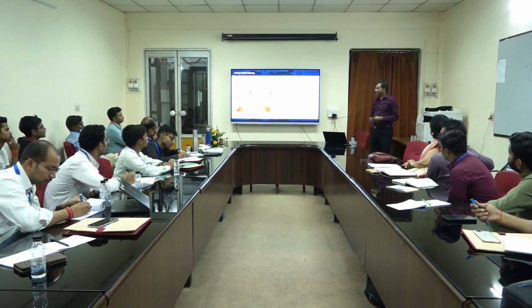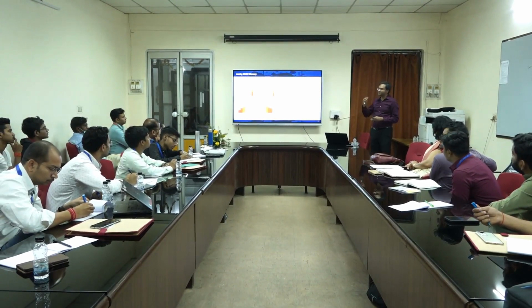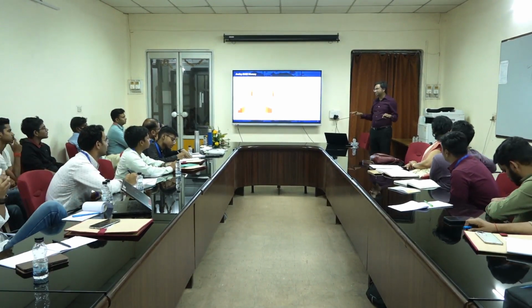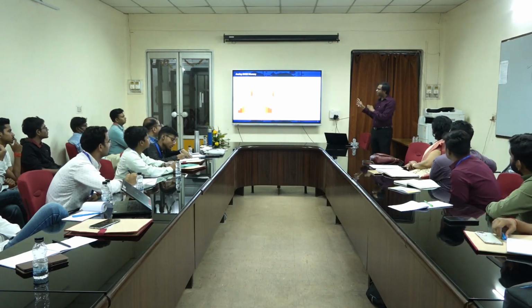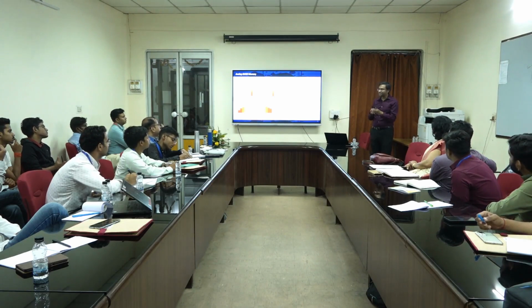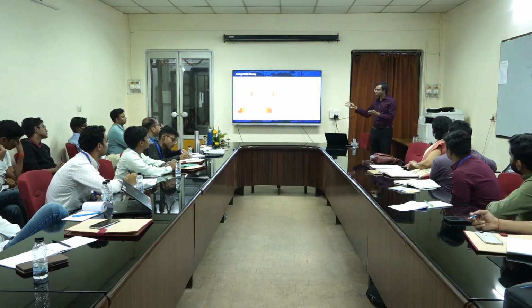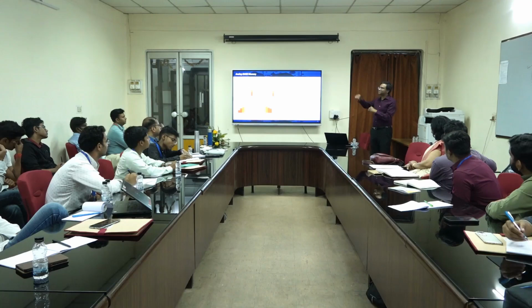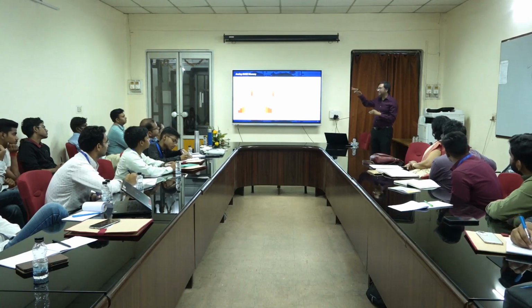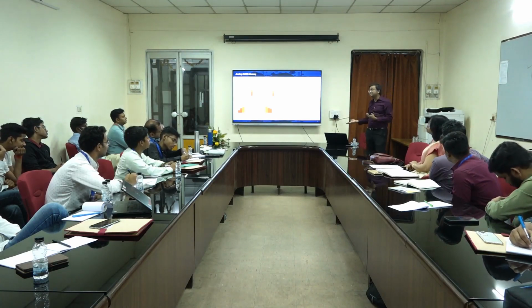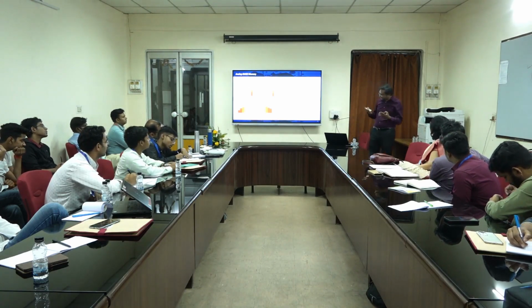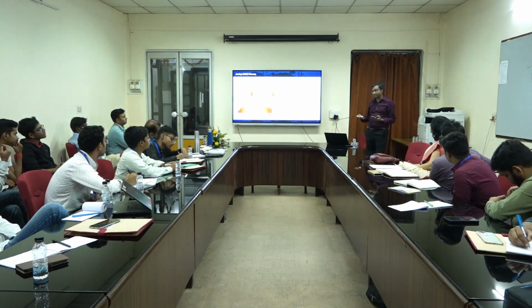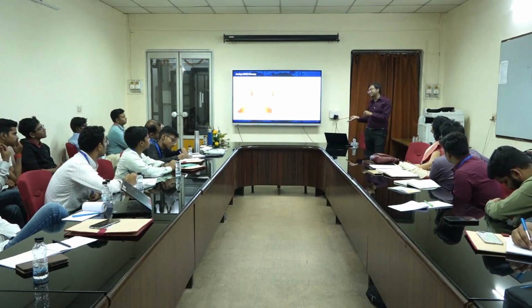These are all monolayers because I told you at the very first, yesterday's lecture that unless you use a monolayer, you cannot scale them. Because we have to have in mind that at the end of the day we need to make the devices very small. And the reason to go to this 2D material is to make them thin. Now, if I start making a transistor with a very thick MoS2, I lose the purpose. Why not then use silicon? Because silicon can already be 6 nanometer thick, and that's our FinFET technology. So we have to use thin layers of MoS2 and WSe2, right? That's the very basic, because that is where the advantage of 2D material lies.